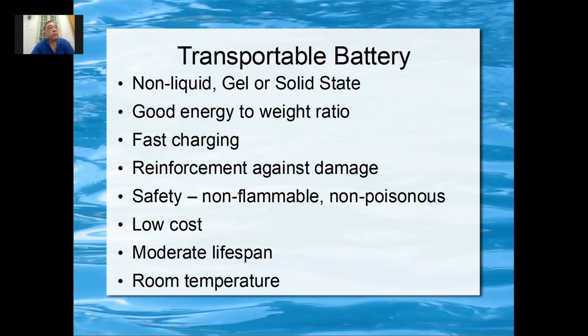So sometimes you talk about battery that is part of the frame. They call it structural battery. So instead of having a structure like the casing, the door of your car, you make the door into a battery, or make a battery into a door. Then you don't need to have a space for the battery, because the battery is the door. The shape of the door is the battery. But there's a problem. Somebody bangs your door, damages it, then your battery spoils. And some batteries can catch fire.